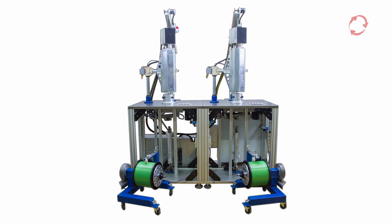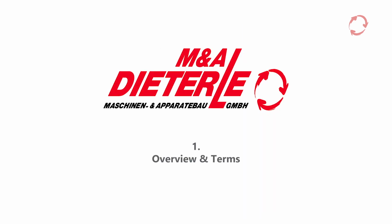The spiral machine essentially consists of two spindles that function independently of one another. Thanks to that, it is possible to wind left and right spirals simultaneously. Please notice that spirals can only be produced by using round monofilaments. The explanations of the terms below are listed in the order of the monofilament or spiral flow, respectively, from bottom to top.